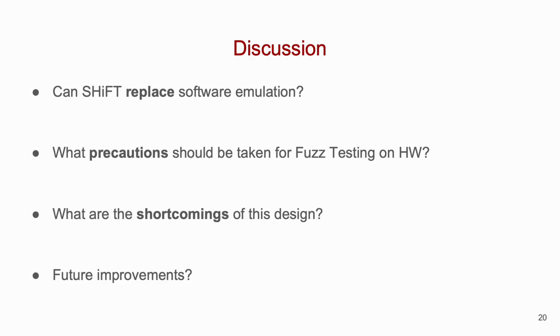Okay, what precautions should be taken for fuzz testing on hardware? Well, fuzz testing, due to its nature, stresses the hardware, can damage the system, or force it into unsafe states. Therefore, the tester has to implement mitigations, for example, to prevent wearing out the MCU's flash by repetitive writing operations, or avoid testing devices connected to physical actuators that can behave unsafely.